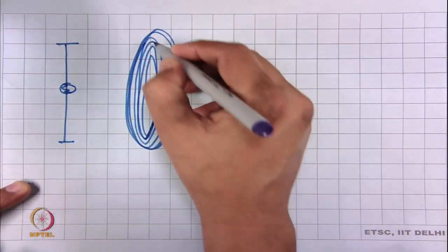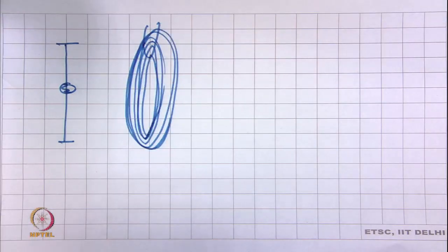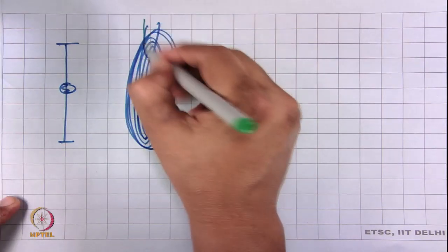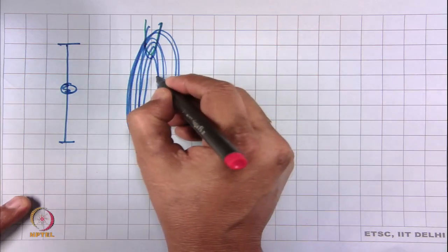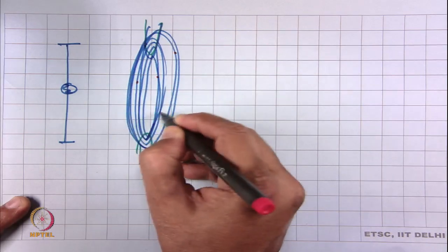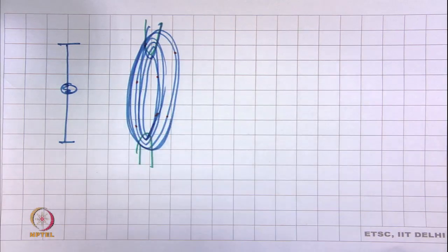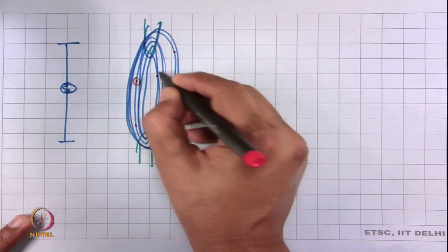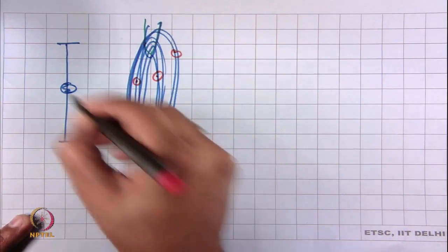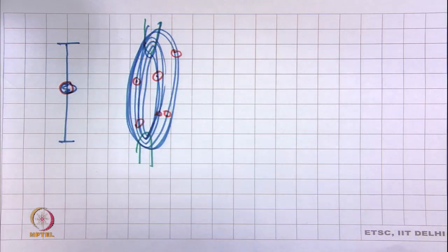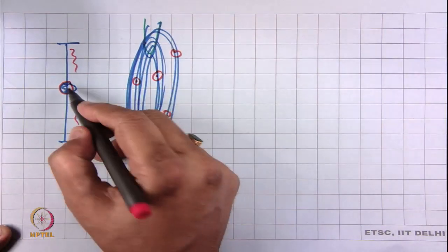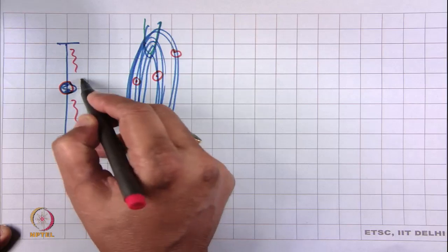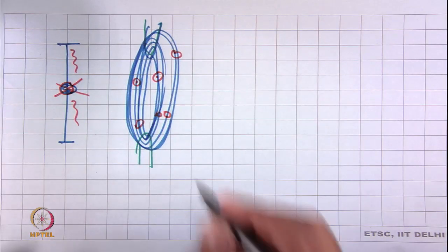large number of repetitions. Now, this is what we are doing, these are the jaws, this is the top jaw and this is the bottom jaw. Here this yarn has different weak spots. In single yarn strength there is only one weak spot. We do not have any idea about the other weak spots which are a little bit stronger than this point. We are not getting any idea. It breaks and that is the end of the test.